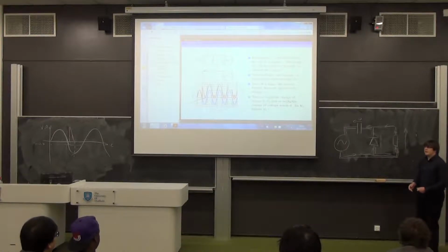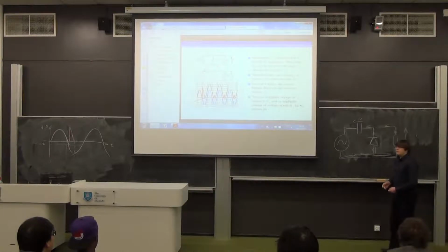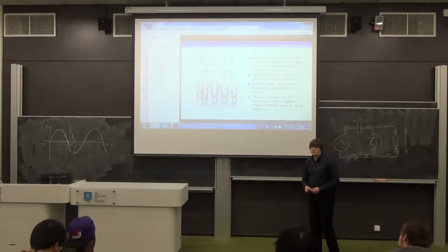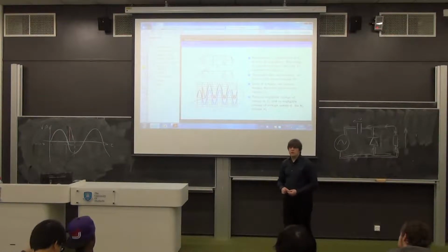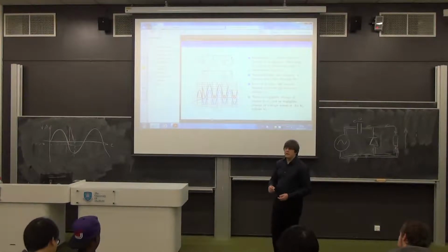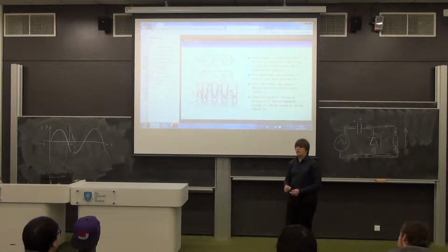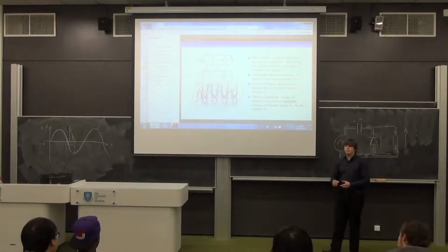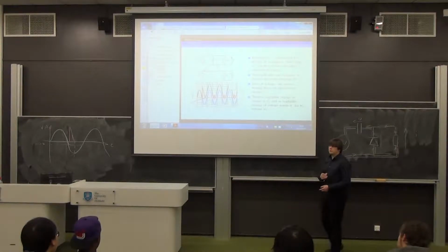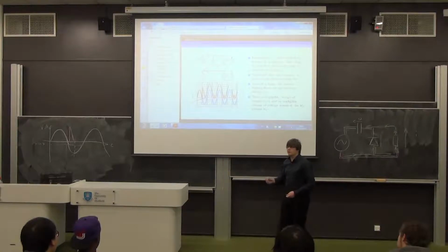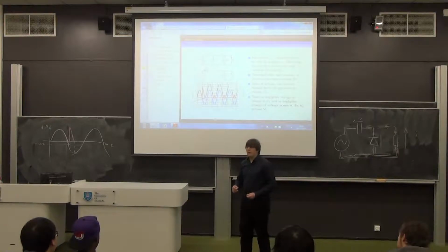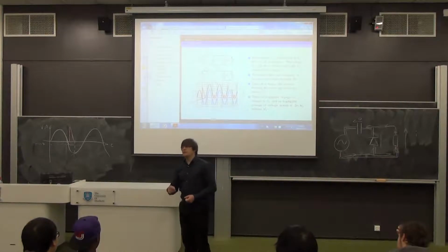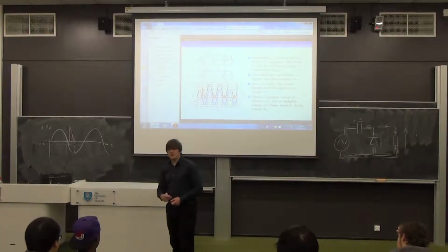That's important later because a lot of rectifying applications, which we'll discuss shortly, deal with electrical machines. And in the case of electrical machines, you have an inductance usually, which is part of the machine, and the inductor wants to keep the current flowing, and it will put some voltage up to try and make that happen. And when we drive electrical machines with bridges of diodes, which we'll see, we won't see it with machines now, but you will at some point, especially in 307 or whatever it's been replaced with, there will be the case where you think the diode's going to switch off now because the voltage has disappeared, but the current keeps going and that makes the voltage stay. And you'll look at it and go, oh, that's very strange.